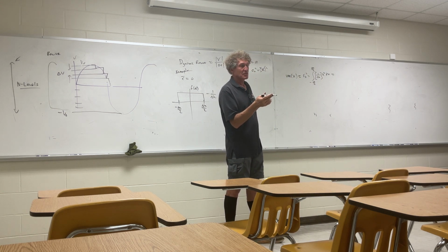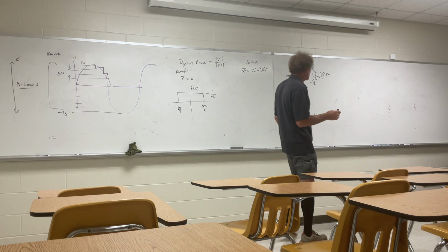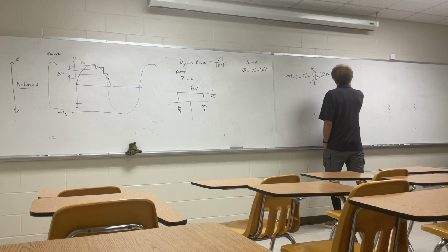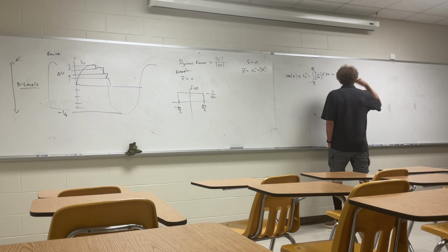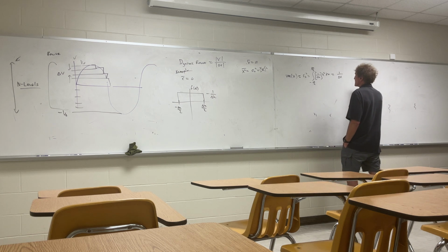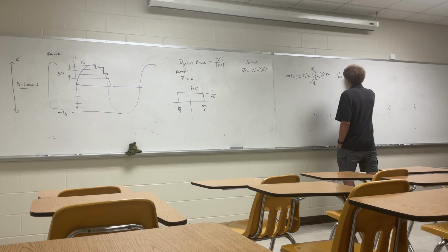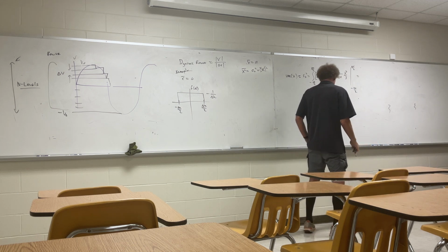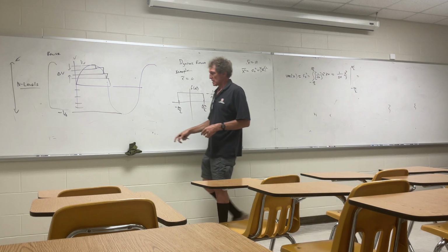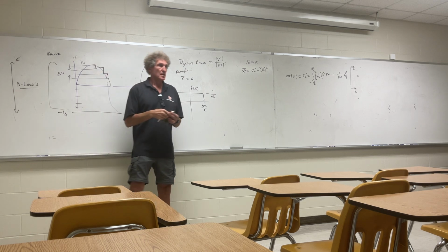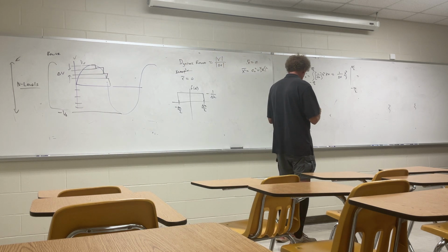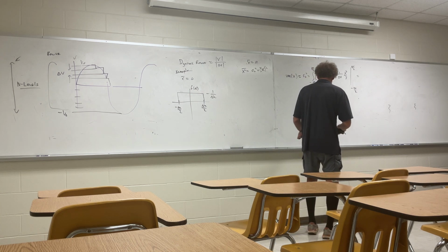It may seem like, who cares? Why are you telling me that? You're going to see in a second, this is important. So if we do this integration, we get 1 over delta x, and that would be the quantization level, you might say the total spread. And then when we integrate x squared, we get x cubed over 3, and it's evaluated from minus delta x over 2 to delta x over 2. Can everybody see this, class? Should be obvious.